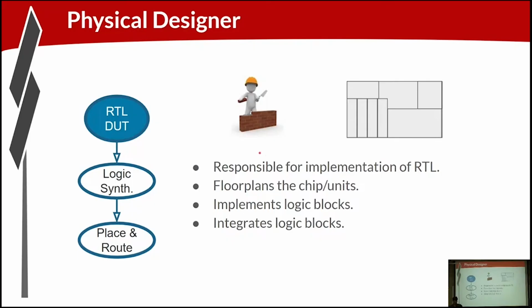So the physical designer will be responsible for floor planning the different units, and then implementing, running the logic synthesis, place and route on these different units, getting the connectivity all correct, and coming up with the implementation of the design. And again, this is all iterative, right? So the logic designer is working on the RTL, the implementation team is running logic synthesis, place and route, they uncover timing issues, they uncover floor planning issues, they feed that information back to the RTL designer, and it's a lot of back and forth.